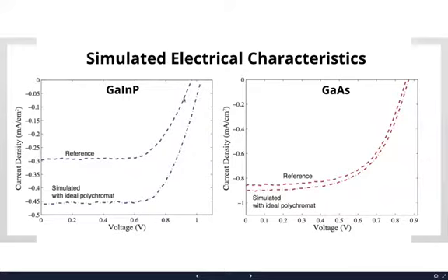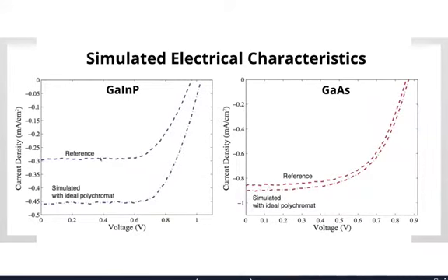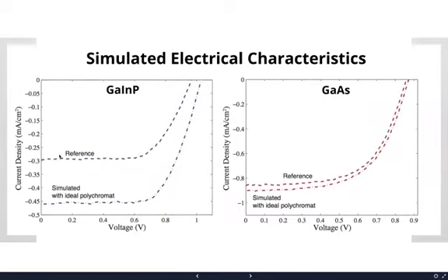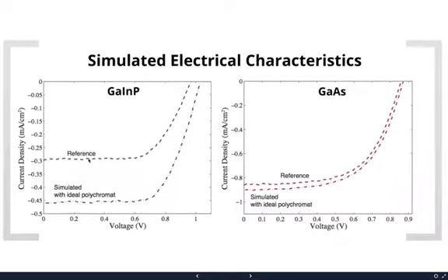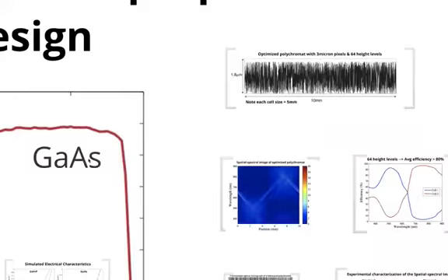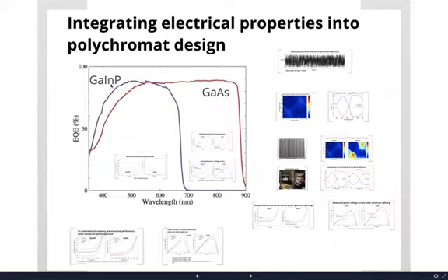And that is primarily to do with the concentration. And for the gallium arsenide, the decrease is much less, primarily because you're already absorbing most of the light. This is more dramatic because it's not absorbing all that extra light very efficiently. Remember, let me explain what I mean. Remember, the gallium indium phosphide cuts off around here, right? Beyond these photons are not absorbed. So this is completely wasted. And with the polychromat, these photons, which are not absorbed by gallium indium phosphide, are redirected to gallium arsenide. Okay, so it's not wasted.